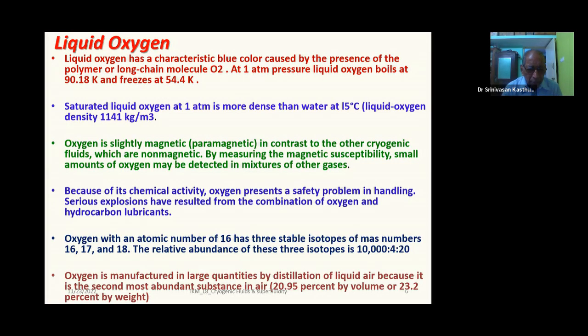Oxygen is chemically very active. Oxygen generally presents a safety problem in handling because oxygen can support fire. Serious explosions have resulted from the combination of oxygen and hydrocarbon lubricants.